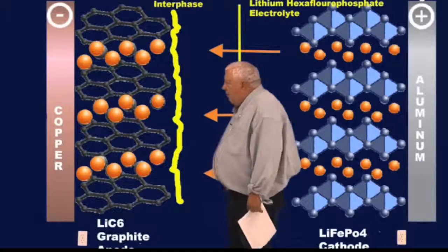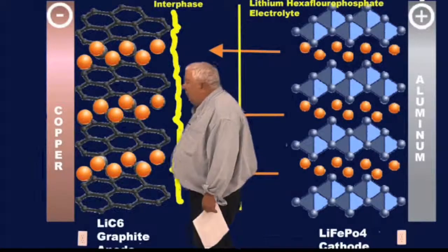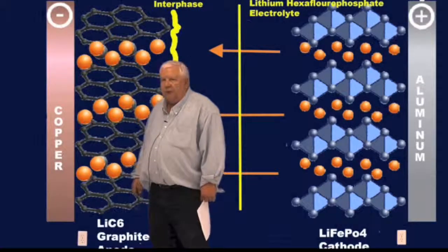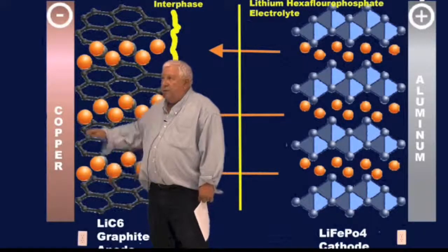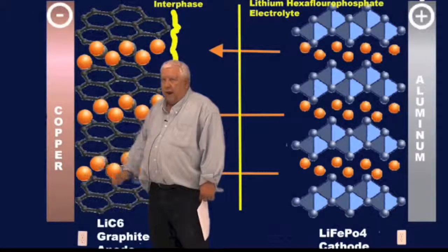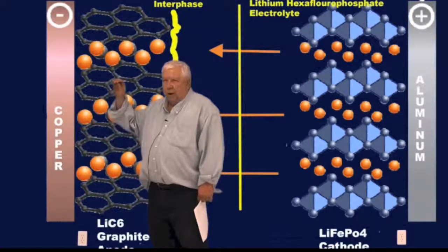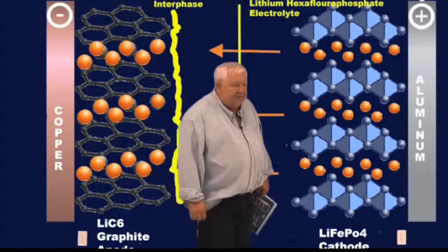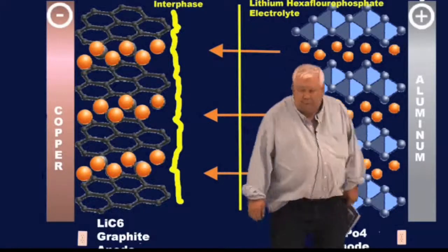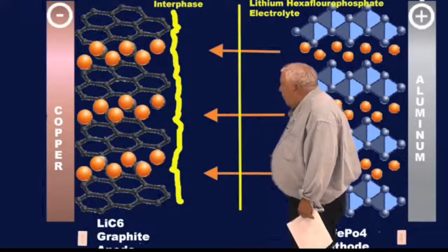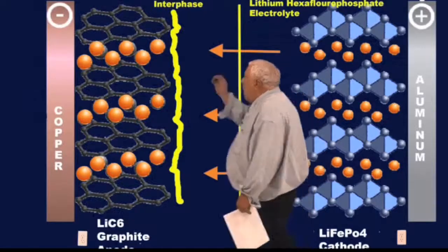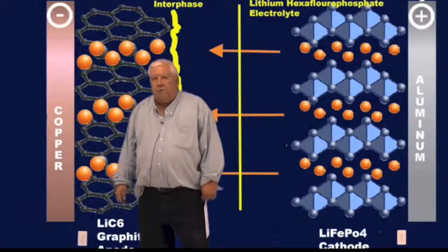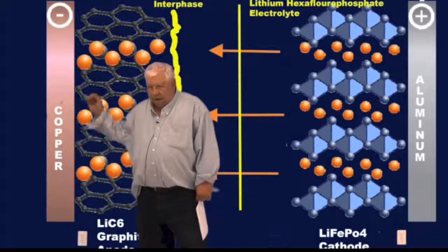And so you have to be very careful in charging again an over-discharged cell. Do it at a low current level and see what happens. What we've observed is that the voltage comes up and then it starts going back down. When it starts doing that, the temperature starts going up. Quit. You're done. That cell can't be recovered. There is no magic procedure. You've lost the cell. And so over-discharge primarily is a function of copper plating on the SEI, and overcharge is primarily a function of iron dendrite growth.